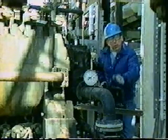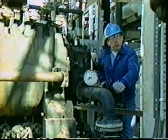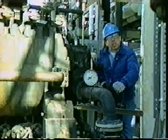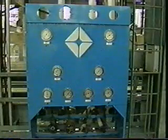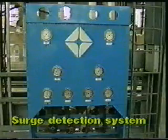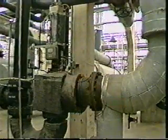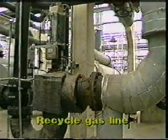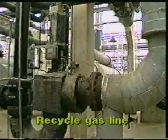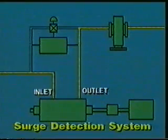So some kind of protection must be used to prevent this from happening. That's why you'll find most compressors use a surge detection system. The surge detection system senses discharge pressure variations and initiates a compressor shutdown in the event of a potentially serious condition. A surge control system can also be installed that allows discharge gas to be recirculated outside the compressor to the suction side. The objective here is to keep the flow above the surge point.